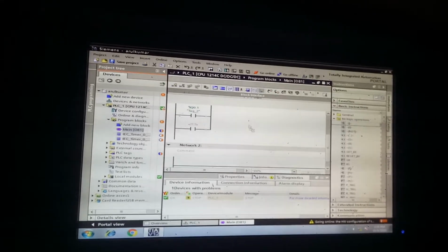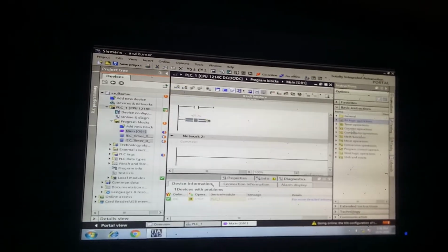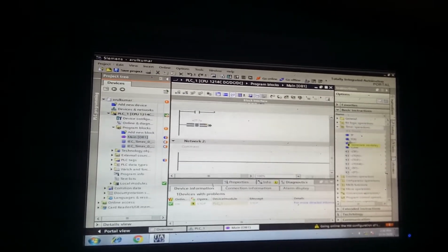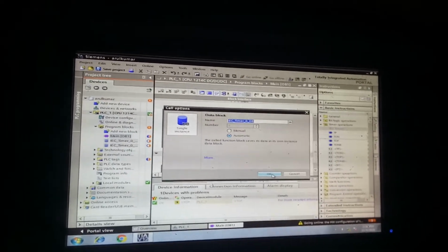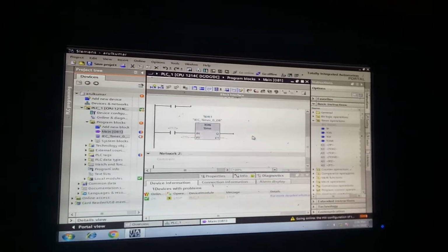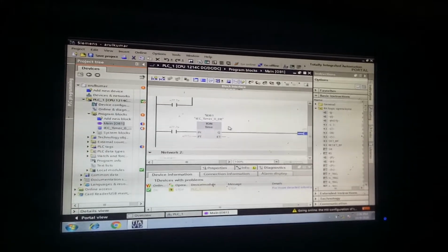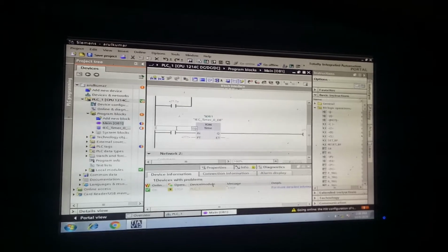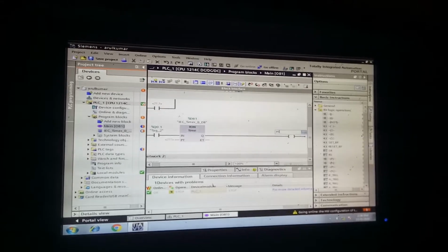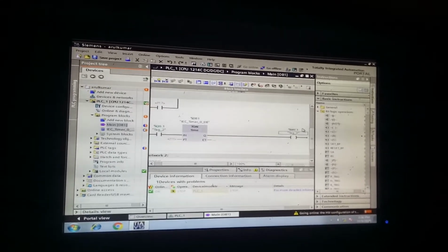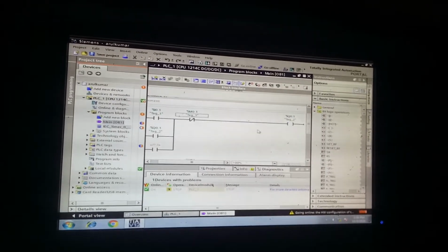Next one here I go for another. Next I go for the timer operation. So go for timer, T on timer. The timer will be different here. Go for automatic. Click OK. This will produce an output, so give the output here. Again here give Q 0.1. The output will be M 0.1. The same M can be here. I go for disconnecting, or breaking, the previous circuit with M 0.1.